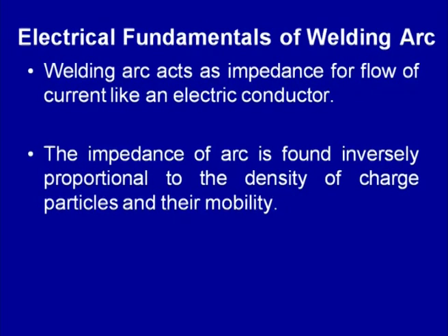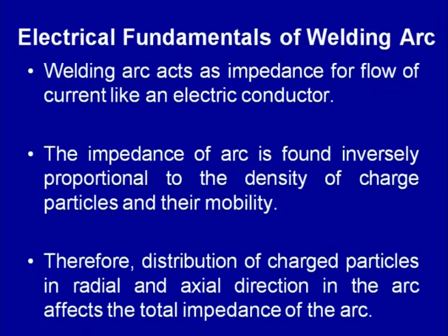Here the impedance for the flow of the current in the welding arc is influenced mainly by the density of the charged particles and the way by which they are moving in the arc gap. The higher the density, the easier will be the flow of the current, and similarly the greater the mobility, the better will be the flow of current. So, if the charged particles are uniformly distributed between the electrode and the workpiece, then the impedance between the electrode and workpiece in the gap will be uniform,